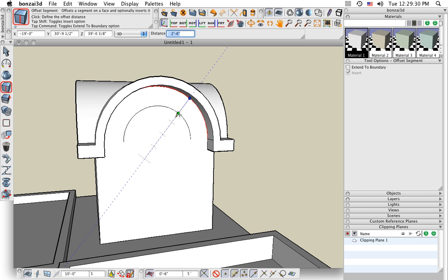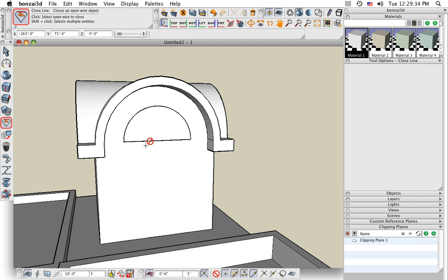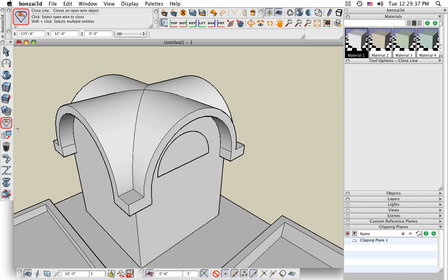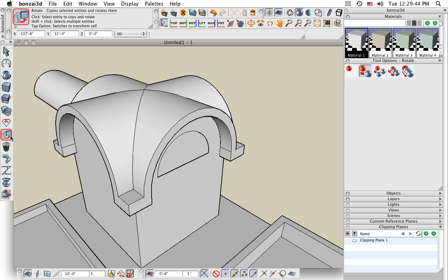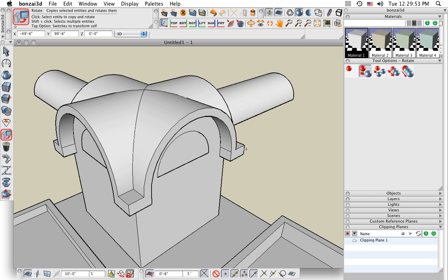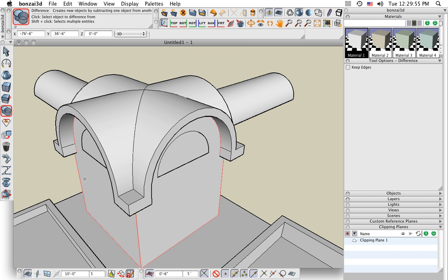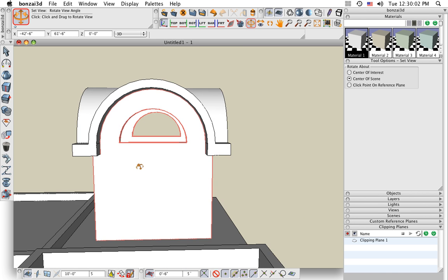Again, offsetting derives a parallel line. And close that into a semicircular closed shape. We'll extrude that into a solid object that goes all the way through. I'll also make a copy of this by rotating it. Snap to the center up here. Rotate it 90 degrees by snapping to my guidelines. And Boolean one more time these two shapes from the wall, and I have created these openings.